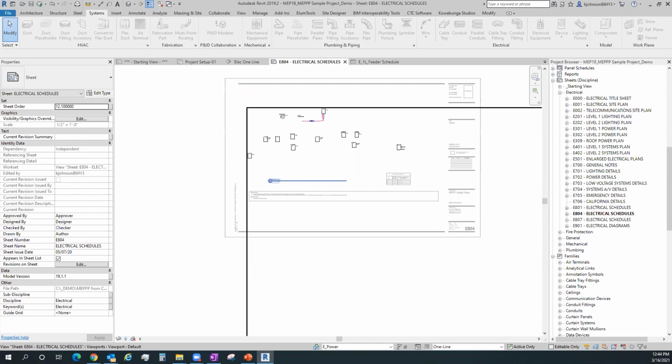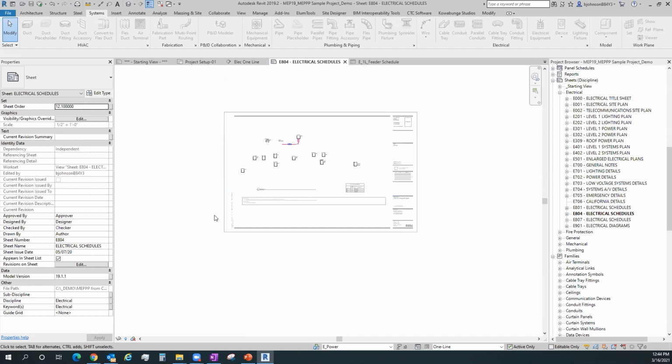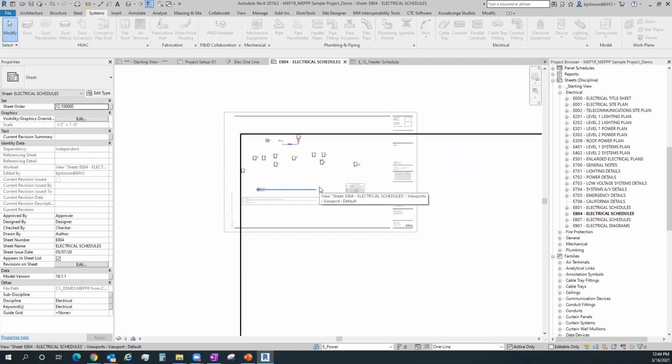So I got 2 more bullet points here, and I want to get done in the next 10 minutes or so if I can, if we don't have any extra questions. One of them was discussion on how the timeline affects how you generate OneLines. So when I think of this process that I've just used, I've done this OneLine very quickly. It didn't take me very long to generate it whatsoever. I can place all those devices and draw some conduits between them, add the right conduit key styles, and probably be done in less than an hour to build that sheet, all things considered.